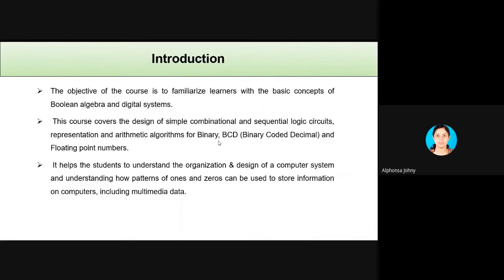The arrangement of these discrete elements of information represent a quantity of information. Say, for example, the digits 2, 3, and 7. When they are arranged in the order, we get a number 237. The discrete elements are represented in digital system by physical quantities called signals. More precisely, electrical signals such as voltage and current. The present-day electronic digital system have only two discrete values. They are 1 and 0. That is binary system.